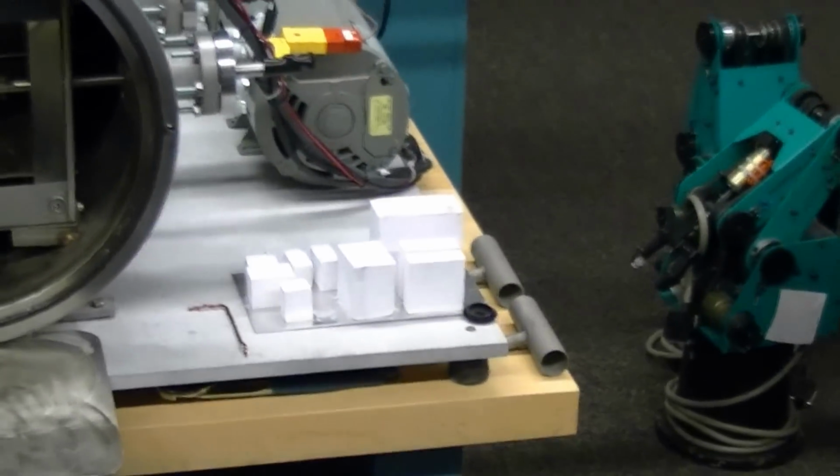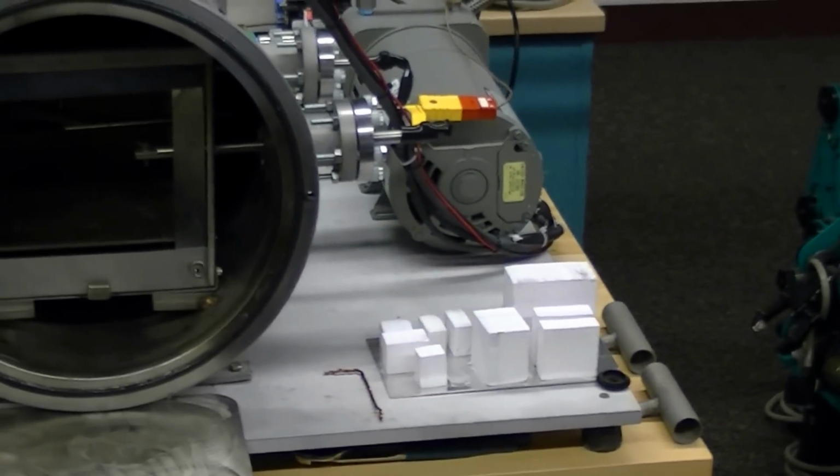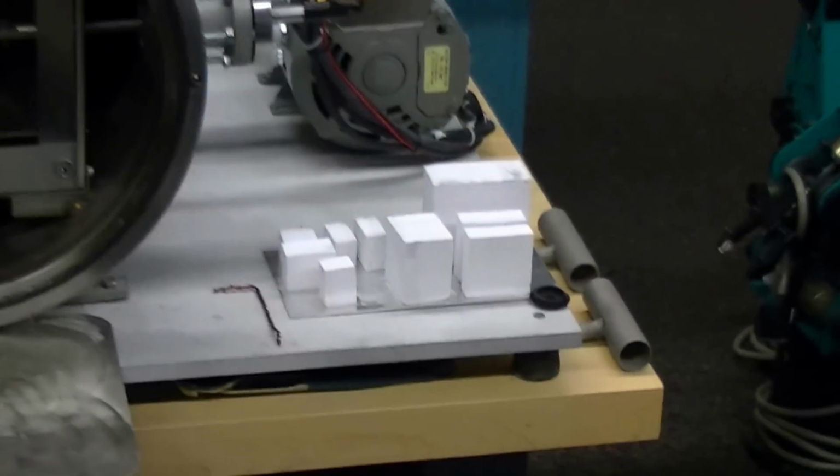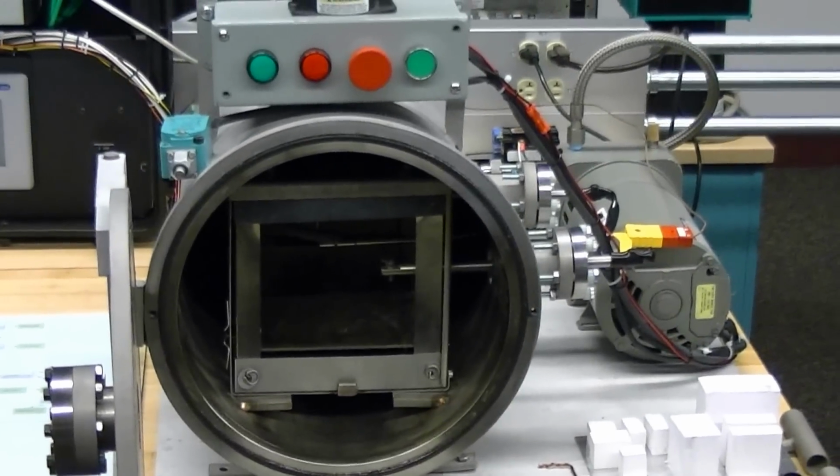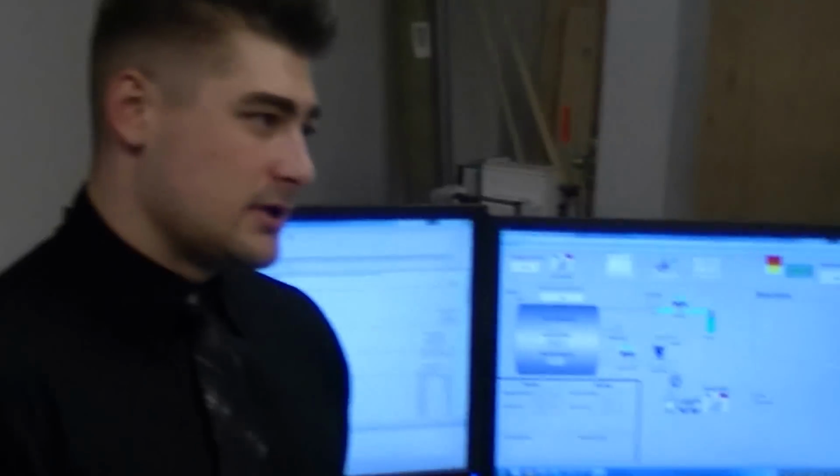And the point of the system is to saturate the ceramic with water before putting it into the system. You take a mass weight of it, see how much the piece weighs. You put it into the chamber for processing, and then the ultimate product is going to have a change in weight based on the water that was evaporated. The evaporation happens based on a heater element inside, and gas flow that comes from a process variable.